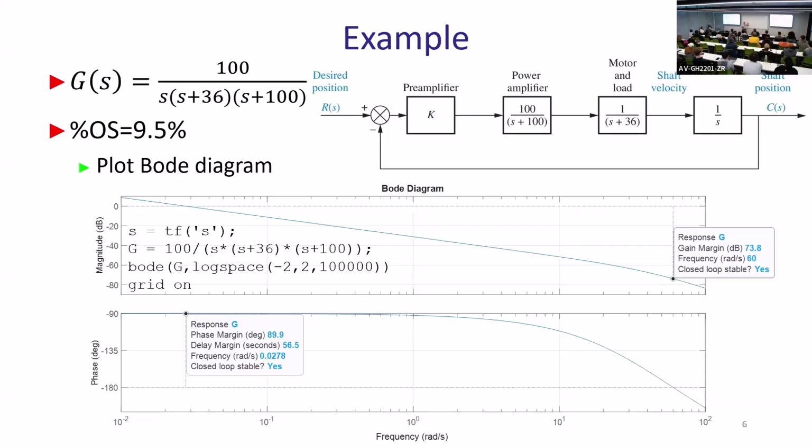And then you send, for example, a step response to each subpart of the system and see how it responds. So based on the settling time and overshoot, you can identify, for example, two parameters. And then, using different frequencies, you can identify the Bode plot of that. Based on the Bode plot or step response, you can identify some parameters of the system. And those parameters you just put in as your transfer function.